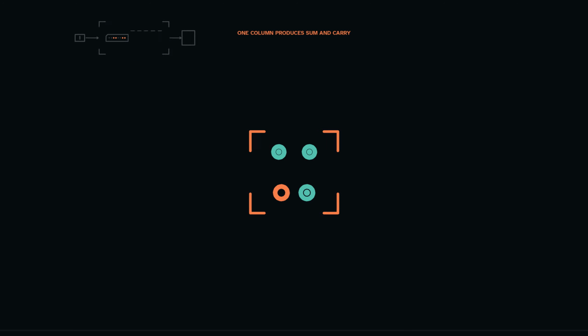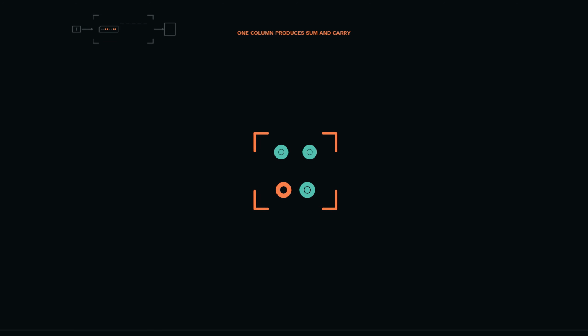Begin with 2 input bits and no incoming carry. 0 plus 0 gives sum 0 and carry 0. 0 plus 1 and 1 plus 0 each give sum 1 and carry 0. 1 plus 1 gives binary 1, 0: sum 0 in this position and carry 1 to the next.